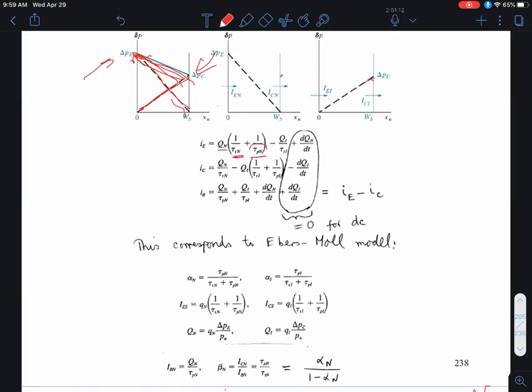Okay, so that's my base current over here. So that's my collector current, IC, plus IB. So the first term is IC, and the second term is IB. Okay, that's IC. That's IB, okay, in the normal mode. But you could also operate the thing in the inverted mode. So now it's QI over tau t in the inverted mode. Now all of this is the DC part.